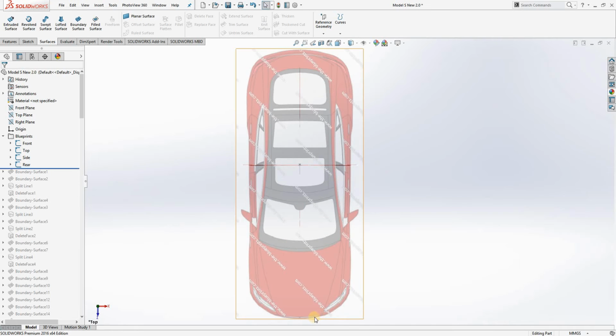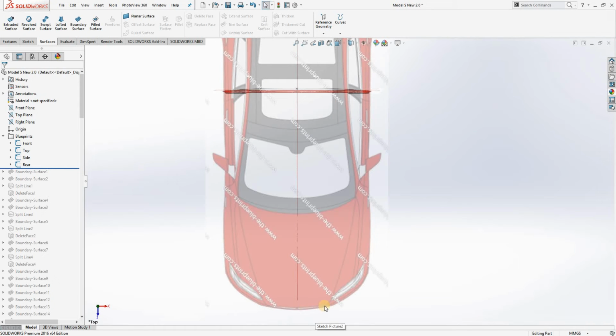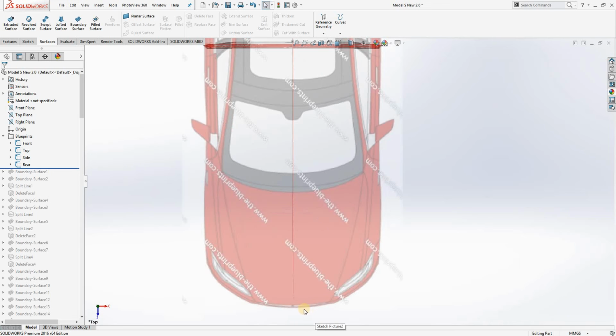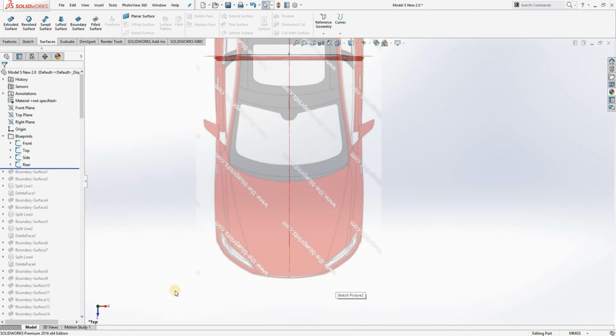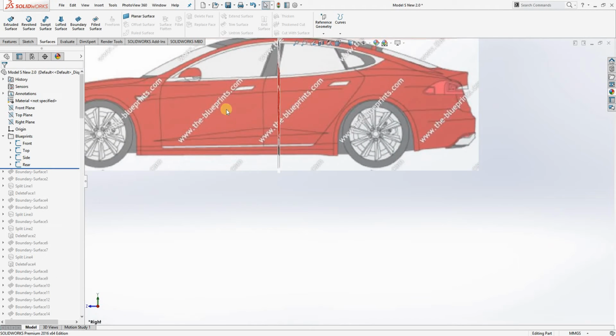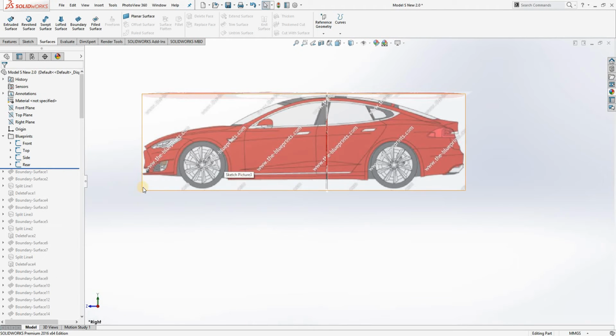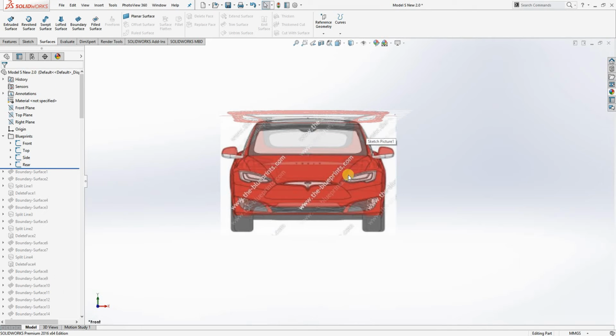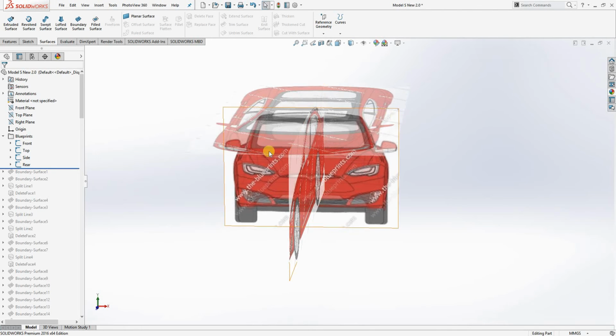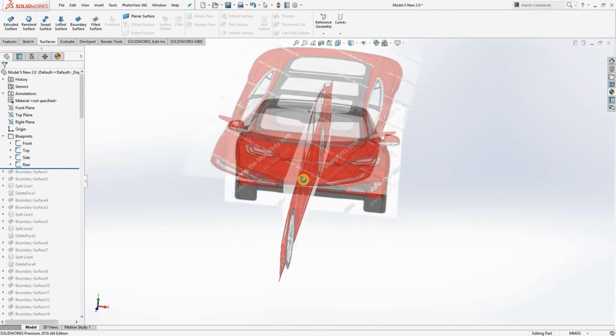My method is to draw curves which match certain areas on the blueprints. It's important that when you import your blueprints, you scale them all correctly. There is an option to set essentially the width of the image, and you want to make sure that all your views are the same scale. So when you're switching between views to make your model, you're working with the same dimensions.